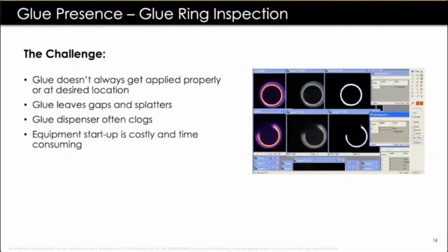We've done another application. I don't have the images here, but if we looked at an area that had thin glue, while it might stick and be adhesive, the problem is that it had to withstand a 9 psi burst test at a certain stage, and you have to wait till the adhesive cures and sets. If it gets downstream and we do not hit that 9 psi burst test requirement, then we have to revalidate.